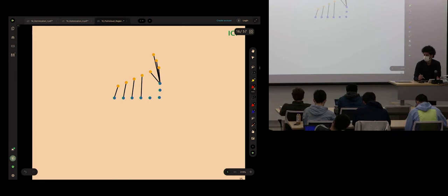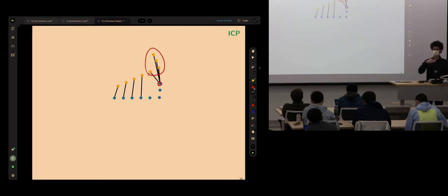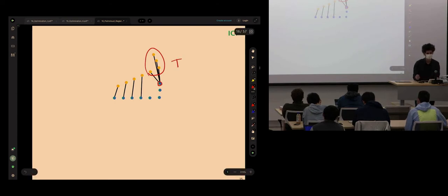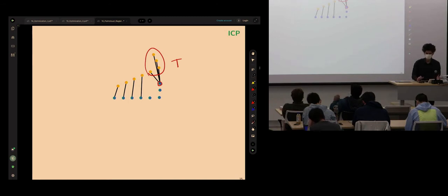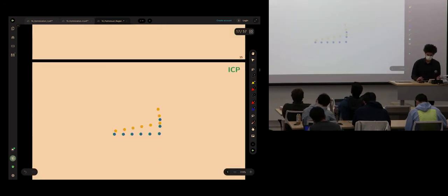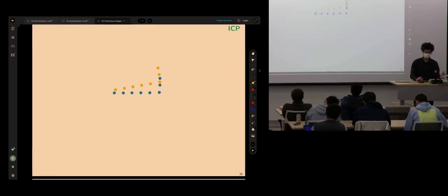If you go with the Euclidean distance, this blue is the nearest neighbor to all of these points. So the residual is evaluated such that all of those points get matched to that single point at this current transformation that we have. And maybe you have some other associations. So we get closer.